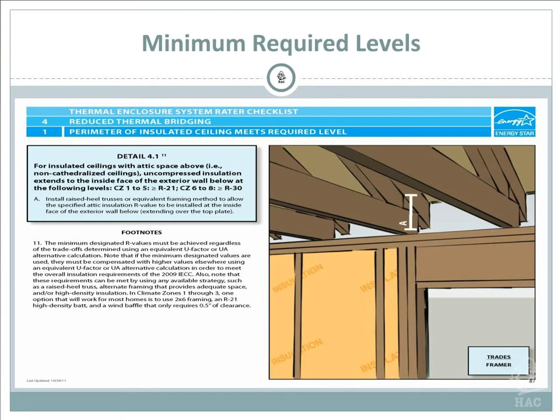So now, when you build these houses and you're building your attic space, you want to make sure that you have enough room in the attic so you can have a continuous R value from top plate to top plate. So again, it gives you the R values, zone 1 through 5. You want to have an R value equal to or greater than an R21.